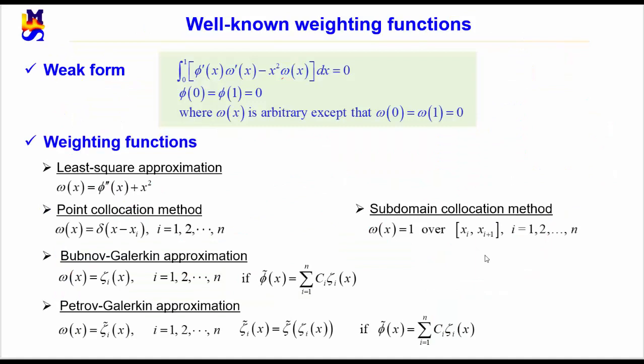In the weighted residual method, we have to apply arbitrary functions for the weighting function to obtain the exact solution. A sort of approximation of the weighting function is thus indispensable. There are several well-known approaches to approximate the weighting function. In least square approximation, the differential equation itself is employed for this purpose.